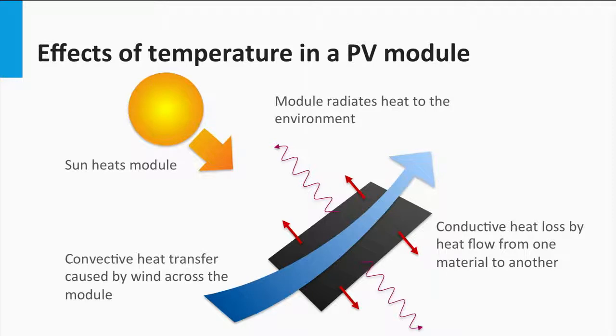There could be several factors impacting the heat flow in and out of modules. Encapsulation of the solar cells is a major factor in increasing the operating temperature of the PV module. The eventual operating temperature of a module will be a result of the thermal equilibrium between the heat generated by the PV module and the heat lost to the surrounding environment.